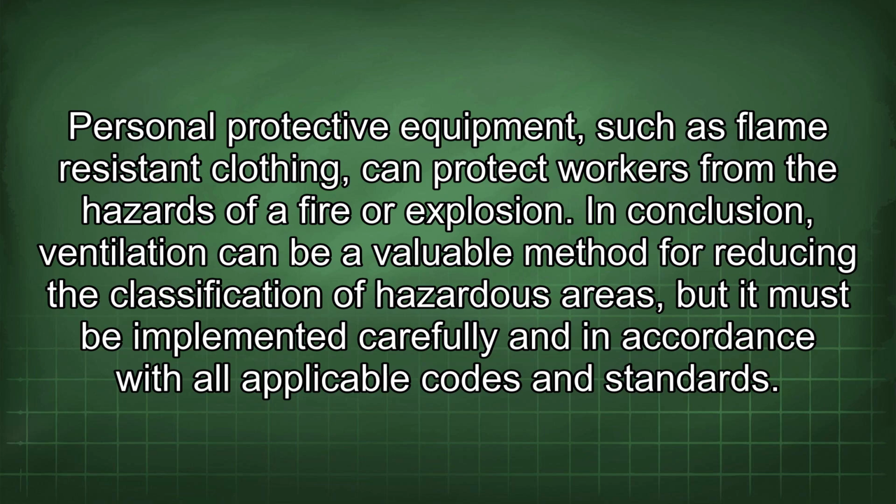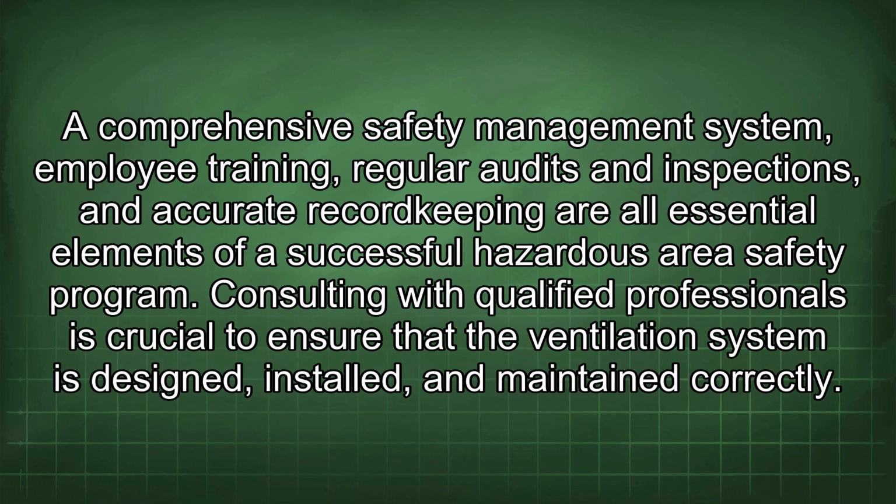In conclusion, ventilation can be a valuable method for reducing the classification of hazardous areas, but it must be implemented carefully and in accordance with all applicable codes and standards. A comprehensive safety management system, employee training, regular audits and inspections, and accurate record keeping are all essential elements of a successful hazardous area safety program.